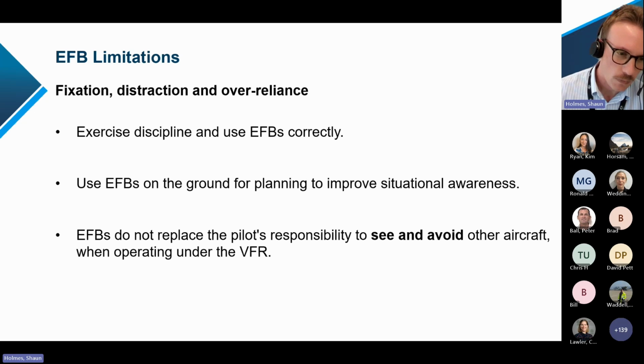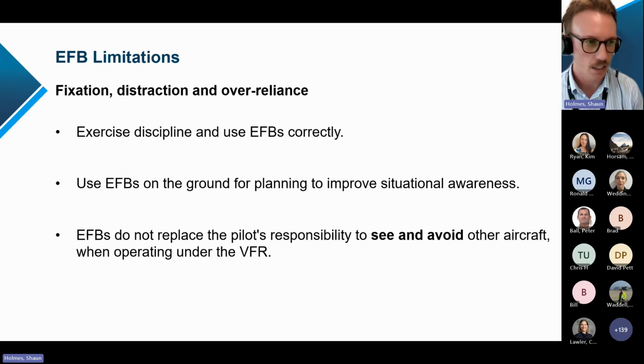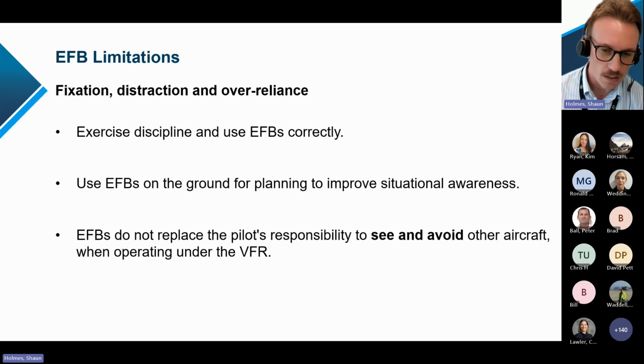So a good way to use the EFB is to exercise discipline and use EFBs correctly. Be very careful of that complacency, because it is so easy to create a significant amount of information 5-10 minutes before you fly and not allocate the time that's necessary to developing that situational awareness. So really the time to be staring at and digging into your EFB is on the ground, to look through that important information and to improve your situational awareness.